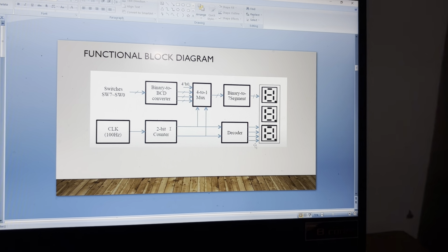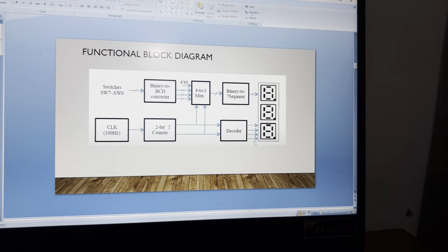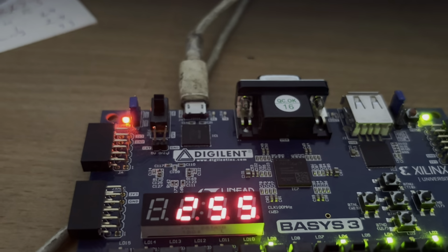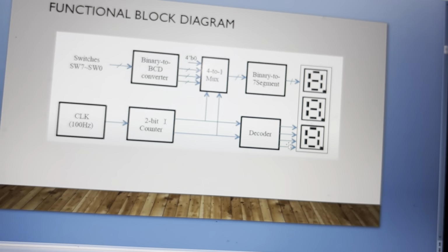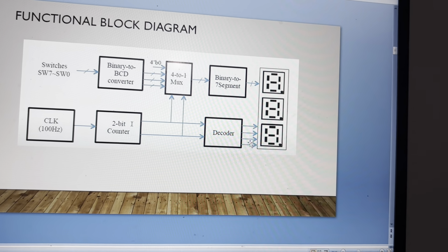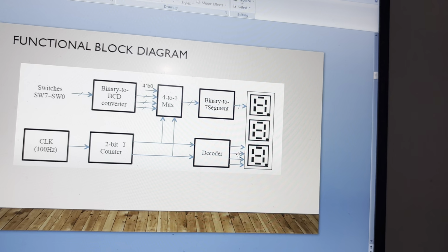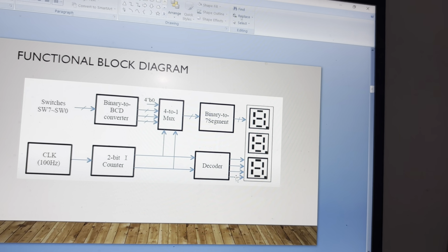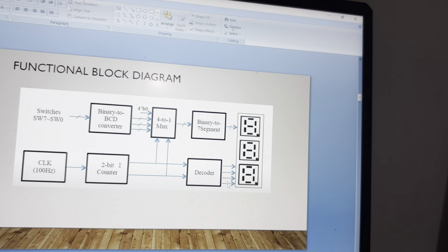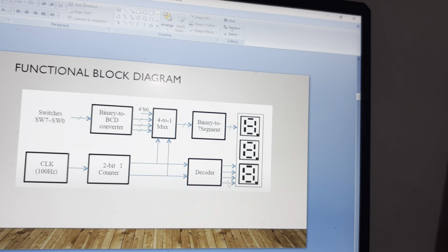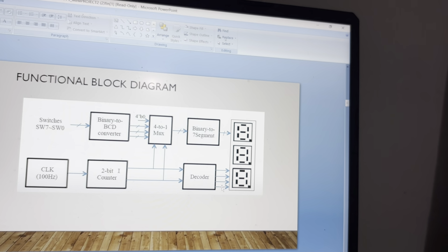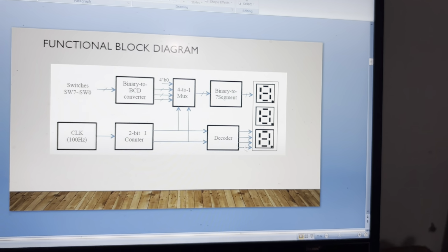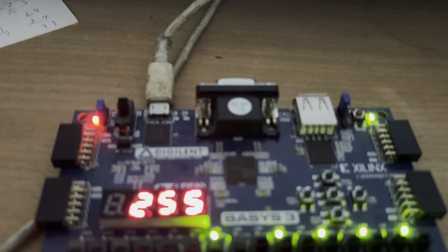The decoder has 4 outputs. These are all enable signals, as we have 4 7-segment displays. We are using a 2:4 decoder, and these are AN0, AN1, AN2, AN3. These are the enable signals. Based on the input, it determines which segment to display. Again, it acts so fast that it is barely visible to note the change on our FPGA board.